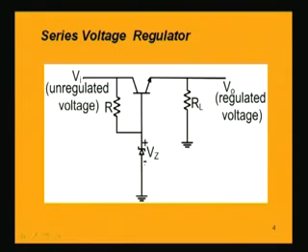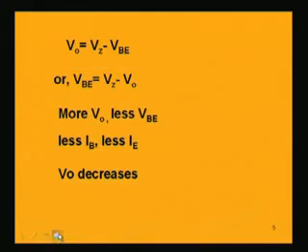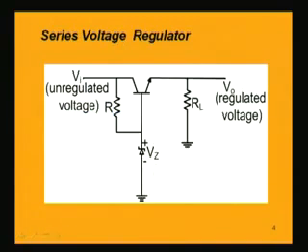Now what will be this output voltage? That can be written as V naught equal to... if we look into this circuit, you start from this ground. Actually V naught's plus and minus is ground, so this will be a loop. Applying KVL, Kirchhoff's voltage law, to this loop, starting from this ground and ending again at this ground, this will complete one loop.